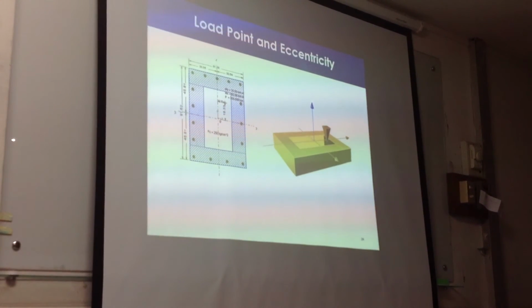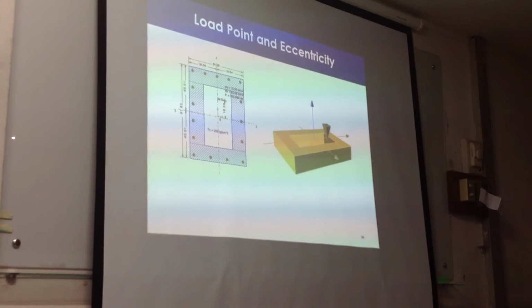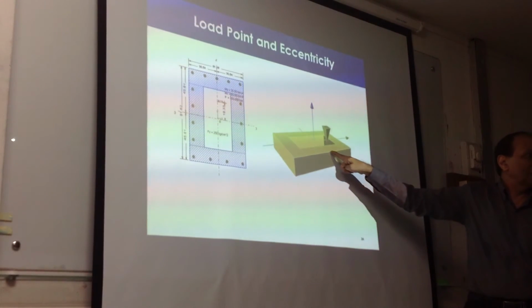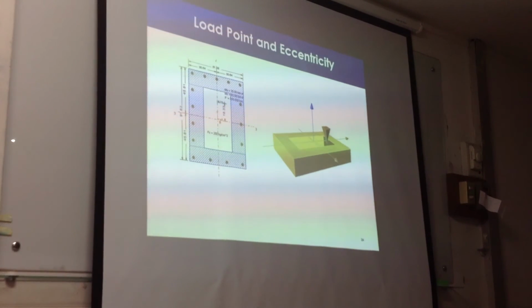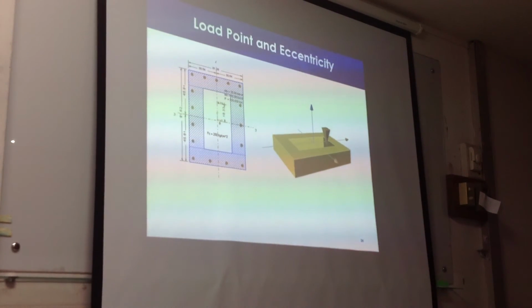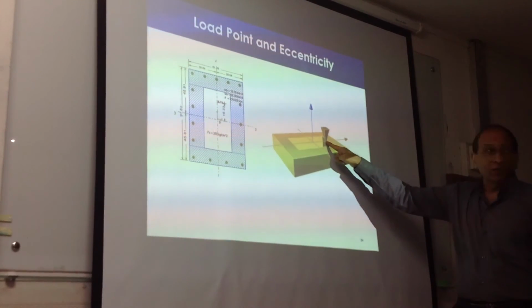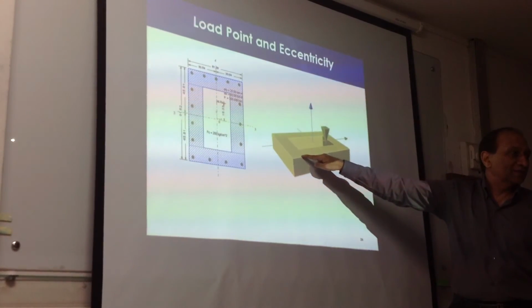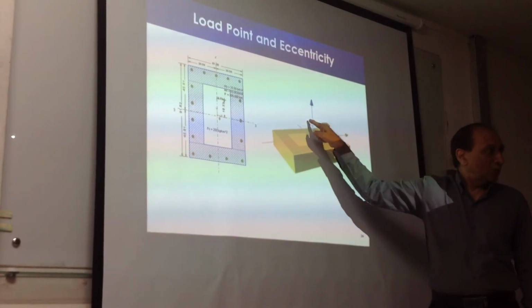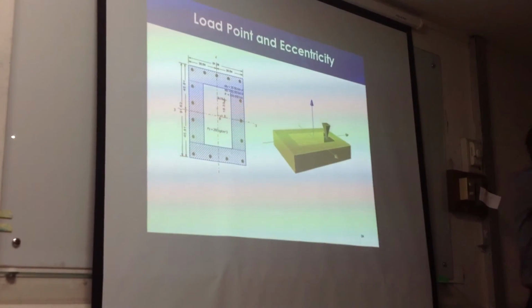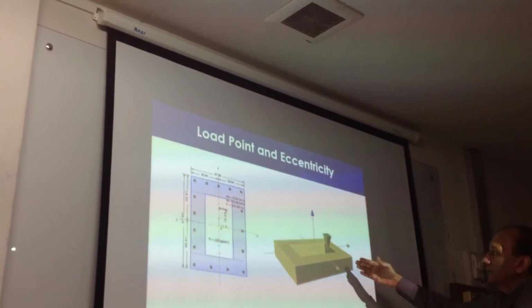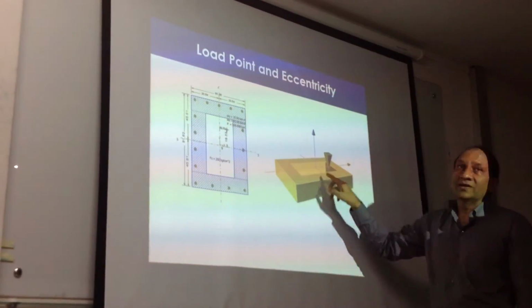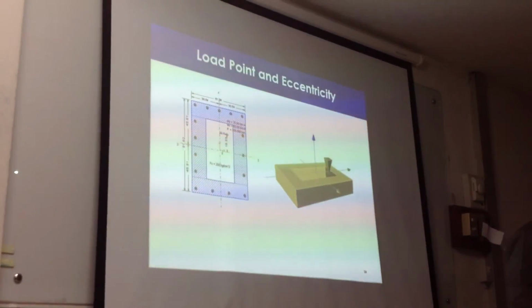And normally, in a typical building, if you have earthquake, wind and so on, the moment keeps changing depending on the load time. So that means for the same cross section, there will be many combinations of deformed shapes that will exist, not just one, right? Earthquake this way, load is here. Earthquake this way, it will shift here. Earthquake that way, it will shift here, and so on. Depending on the moment direction, this load will keep shifting. So that means there could be many locations, and that this will govern the strain profile.